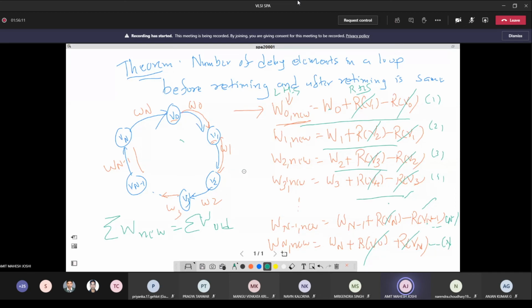I have just applied a retiming concept, but nothing is optimized. From where I started, I got the same. So ultimately, the critical path delay has to change. In the second example, we saw that when I introduce 2D, I have the flexibility to take out a D and rearrange.